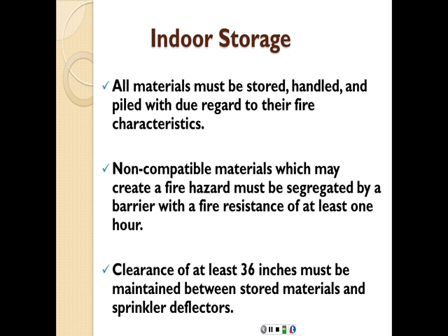For indoor storage, all materials must be stored, handled, and piled with due regard to their fire characteristics. Non-combustible materials which may create a fire hazard must be segregated by a barrier with a fire resistance of at least 1 hour. So the minimum fire resistance in this case to enclose the fire is going to be at least 1 hour. Clearance of at least 36 inches must be maintained between stored materials and sprinkler deflectors, again to allow for the sprinklers to work properly and to spread to the required area.